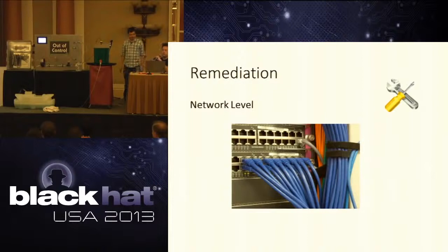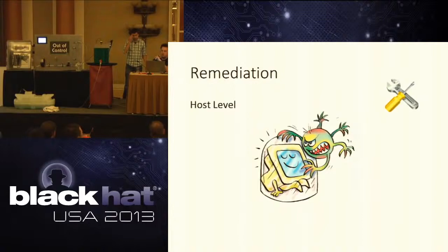So quickly, I'll talk about some remediation. A lot of the security on network security is similar to the enterprise side. Making sure your architecture is compliant and your standard architecture with firewalls, and trying not to have a public IP for some field devices that anybody could just talk to.